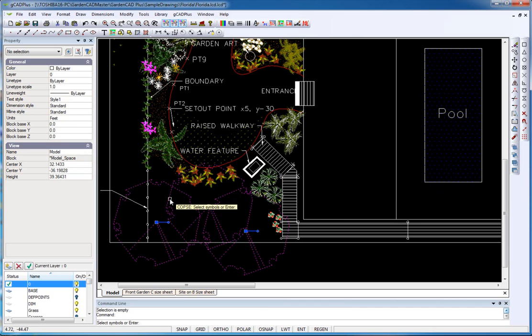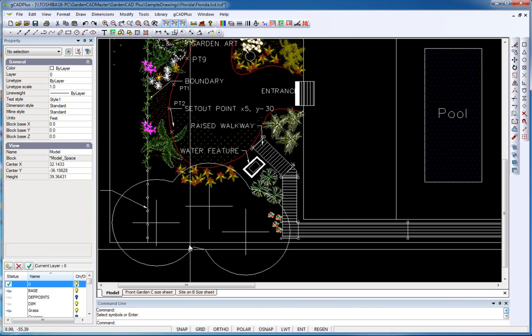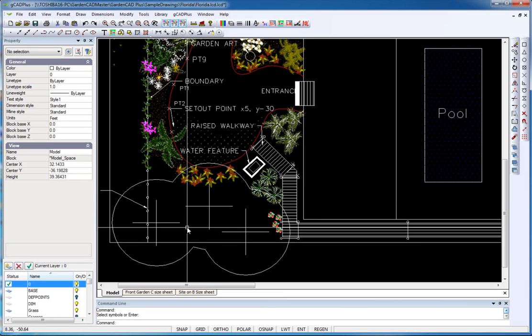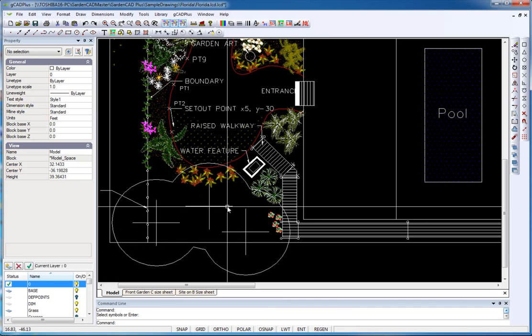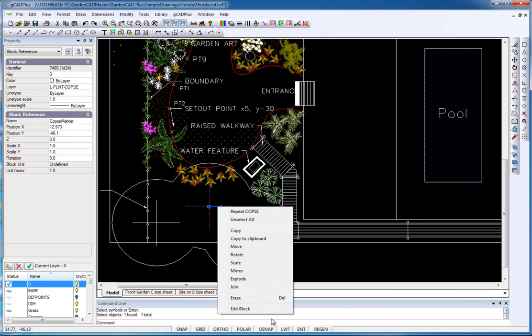the enter key. And what that will do is merge the three into one, and you notice that a relatively large crosshair appears in the middle. Now you can manipulate that crosshair in any way you like. So if we select the symbol, the crosshair symbol now, that's the marker, if you like, that indicates the plants there. A cross is normally used to indicate a new plant. You might want to indicate with a circle that these are existing plants.